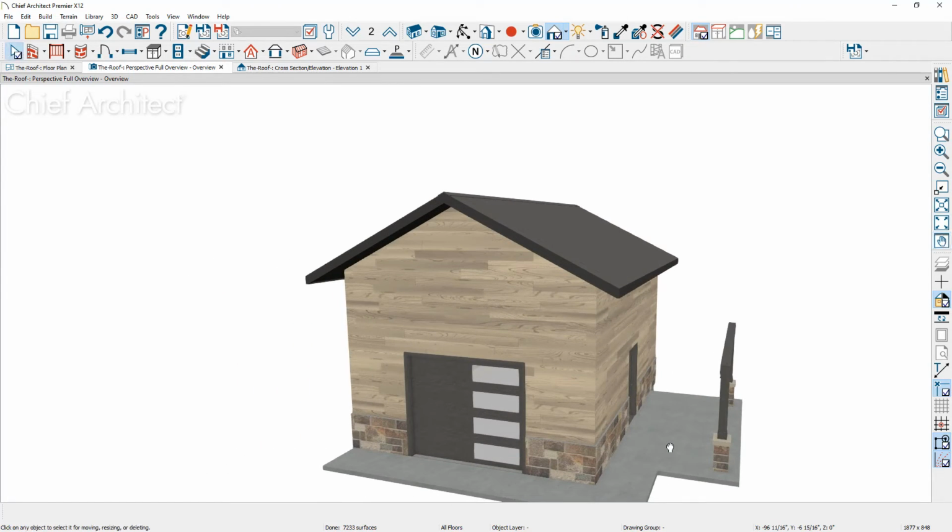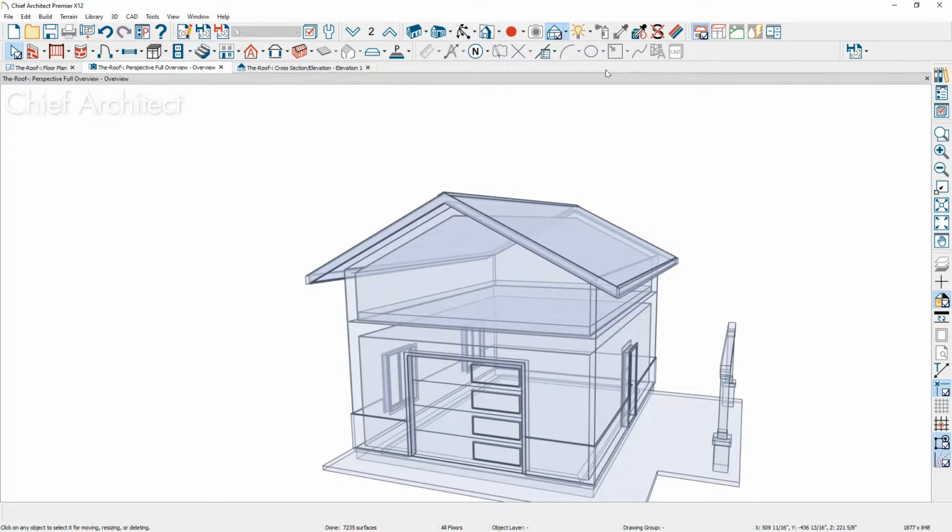So this is called a story and a half. You can toggle the glass house view on and verify what just happened here. And on the sides over here, it would have raised that roof 60 inches on the sides. It's called a story and a half. Oftentimes you'll have a couple of walls in here that would be maybe considered a knee wall, and then you've lowered your roof and built it on that first floor, raised it up off the plate, whatever the predetermined distance is.